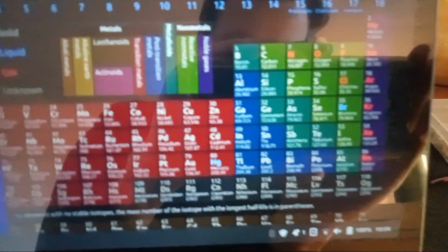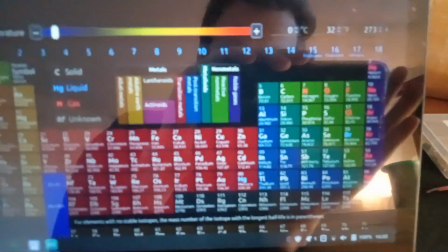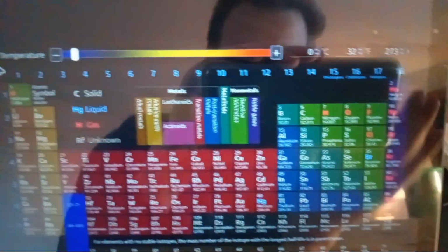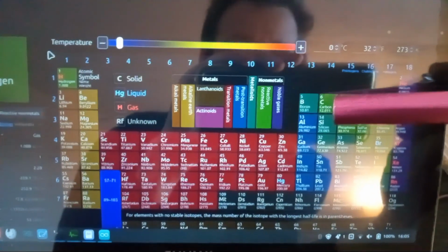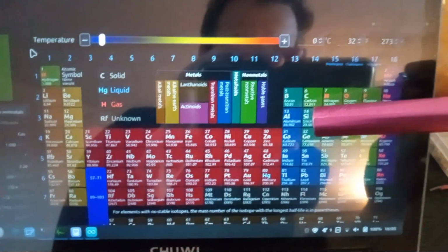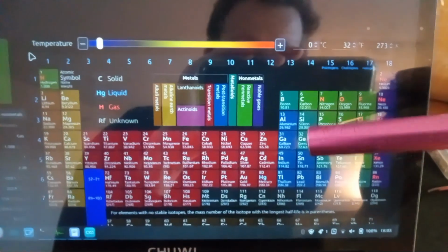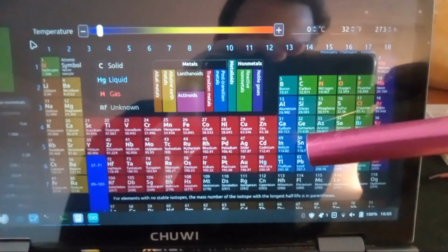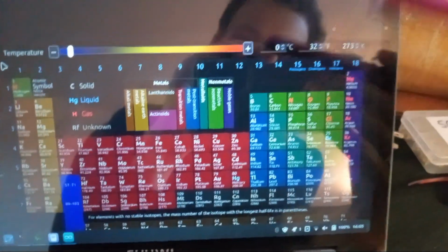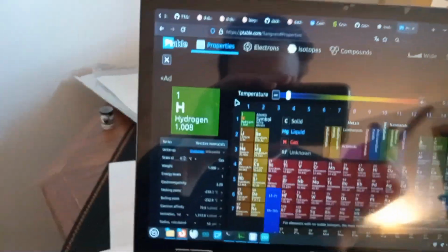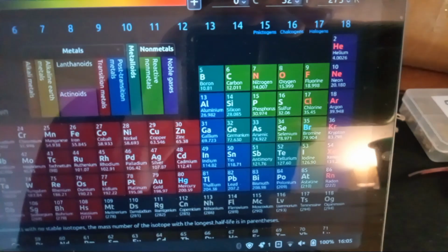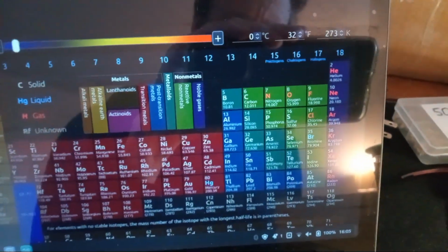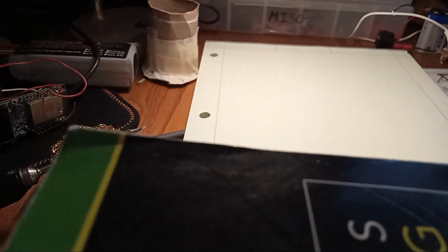Semiconductors are made of elements in this column of the periodic table starting with carbon. Carbon, silicon, and germanium all function as semiconductors. Tin less so. Once you get low in the periodic table, everything wants to act like a metal, with many exceptions. This is not intended to be a chemistry class. Anyway, carbon, silicon, and germanium all have 4 valence electrons. That is, they have 4 electrons that they can share with other atoms.